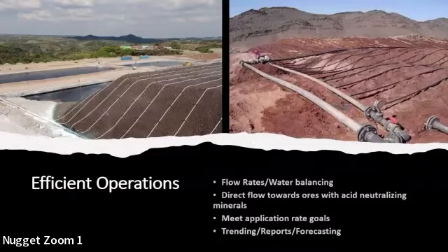Well, we did the same performance over the ROM facilities, and in the ROM facility, they were considered to perform 22 points that were also aiming to go down 25 to 30 meters in depth. But related to the grain size or the blocky material that could be found along the path of the CPTU, the depth that we could get in average was 15 meters. So it was half of what we were aiming to get.